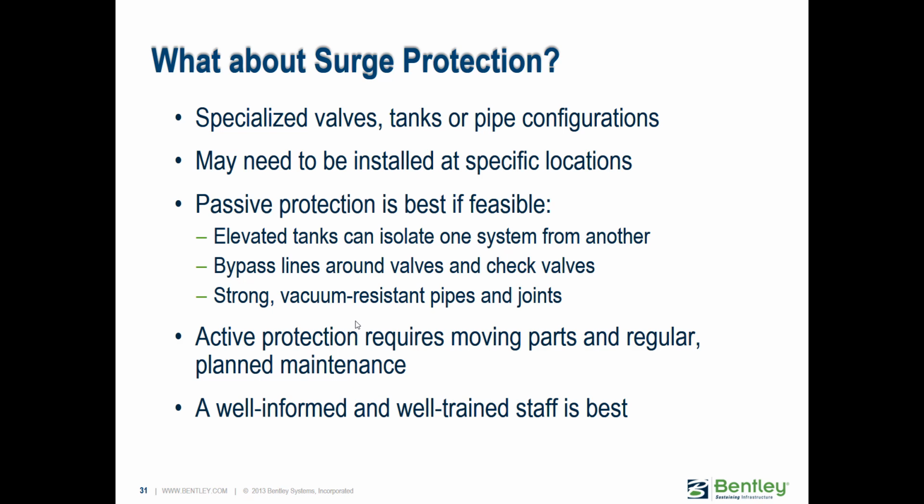And then also, obviously, a well-informed staff is definitely a good investment, because if somebody doesn't realize that they shouldn't be closing a valve so fast, that's definitely a concern. So in addition to all the traditional surge protection that you could put in and simulate in Hammer, it's also very important to have a well-trained staff.